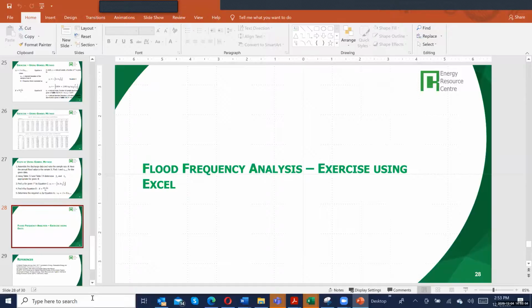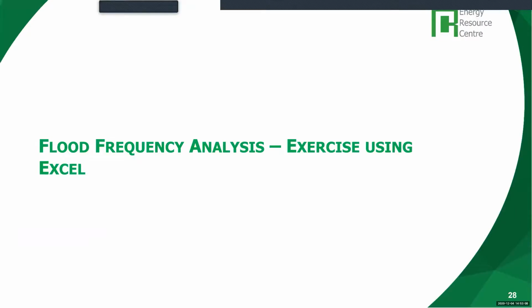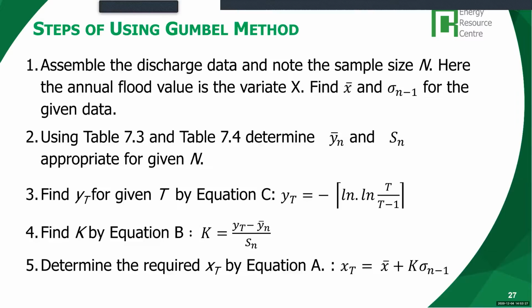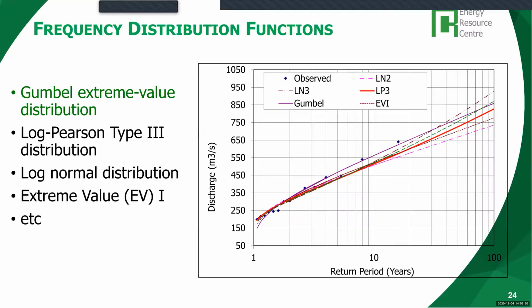Please use your data from Mozambique for any station, the frequency data and the flow data, and try to use the Excel that I have shared and the steps given in the presentation today, and do your own frequency analysis, and we can discuss that.